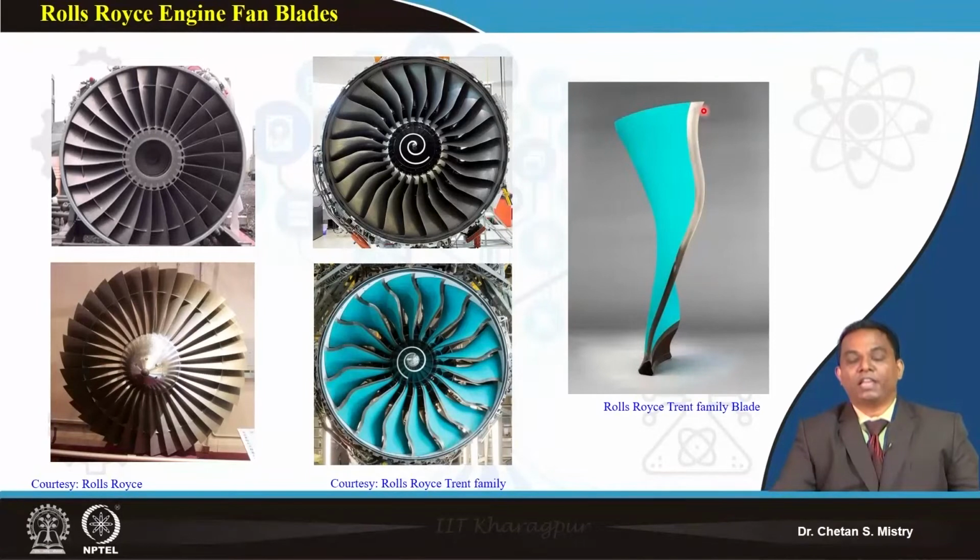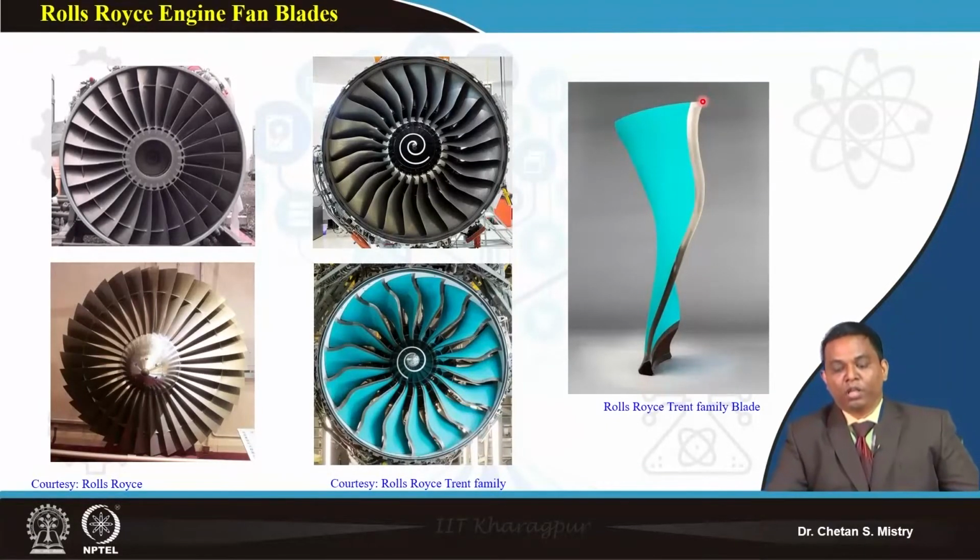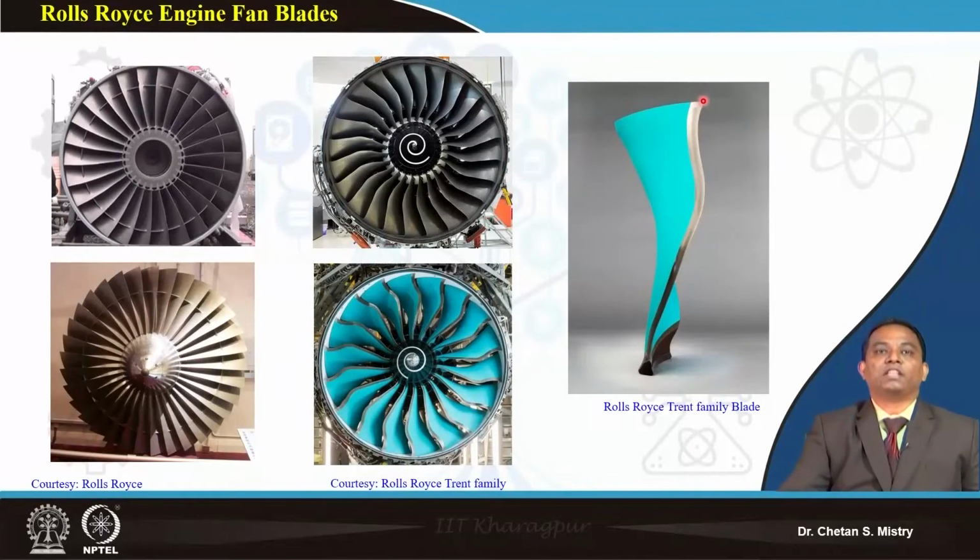This sharp leading edge is there because it has to handle the transonic flow, in the sense the formation of my shock. So this blade will be handling this shock, and that shock will be standing at the leading edge, and that is a special kind of design. And this is a most recent development that these aero engines are doing at this moment.